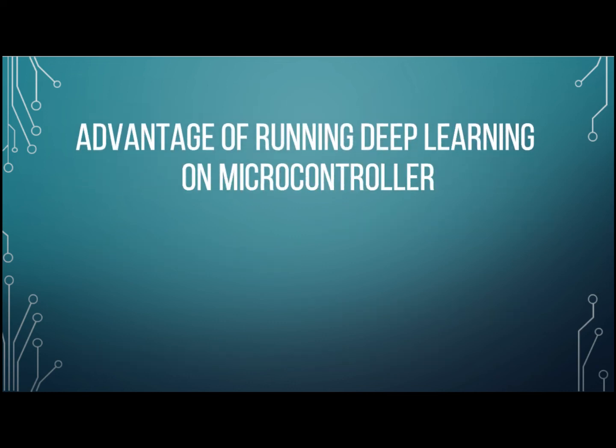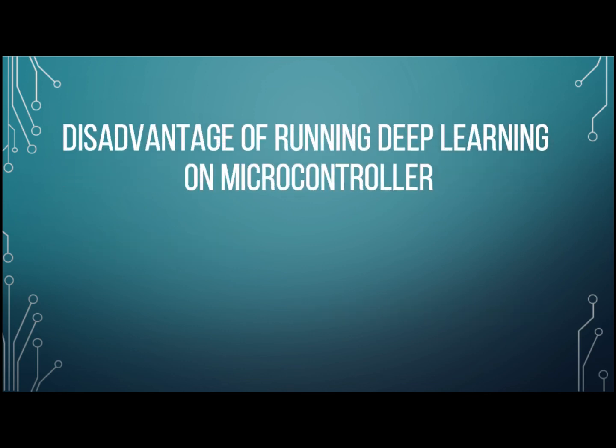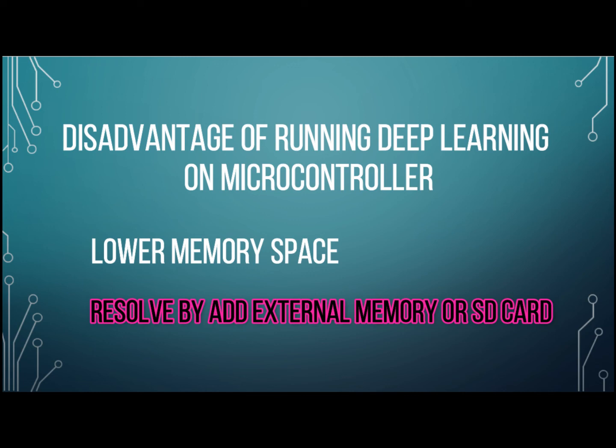So, with deep learning that can be run on a microcontroller, it will reduce the cost to build a deep learning workstation and also minimize the usage of electricity, because the microcontroller board only uses 5 volts to turn on and gets good performance running deep learning. However, because the memory space of a microcontroller is lower than a microprocessor, there will be a limit to running large scale deep learning. To resolve this issue, the use of external memory such as an SD card is needed.